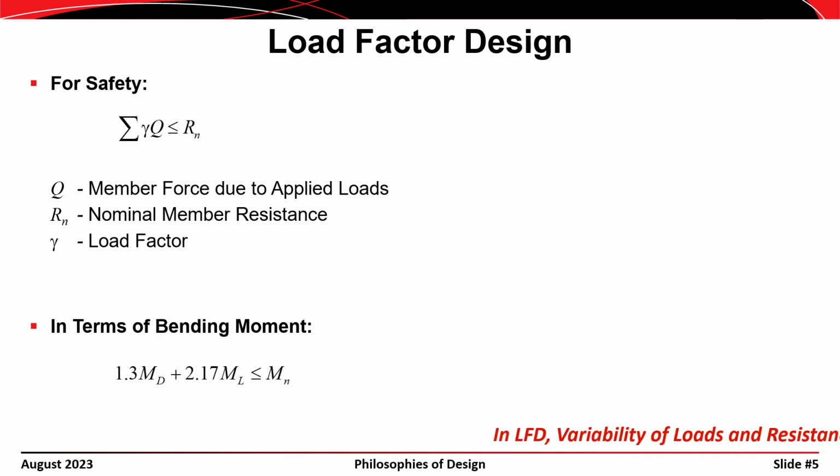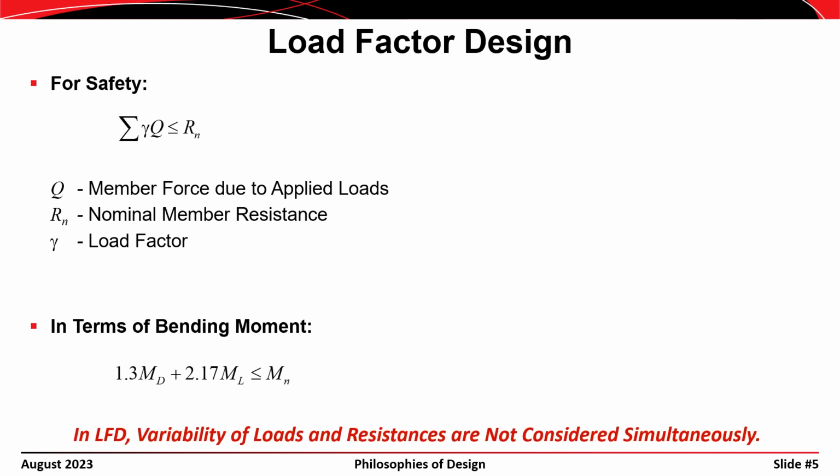Now, load factor design is an improvement over allowable stress design, but it doesn't recognize the variability of the loads and the resistances at the same time. It still recognizes them separately, which is a shortcoming. None of our major specifications use load factor design at this point. The last one really to do so was the old ASCE standard specification, which was based on allowable stress design, but it did have a load factor design alternate in one of the appendices.